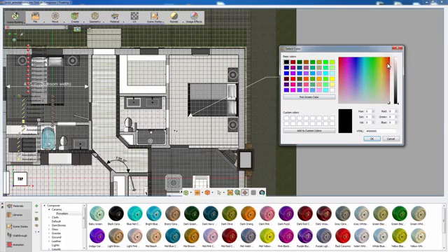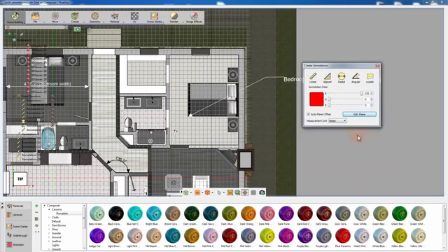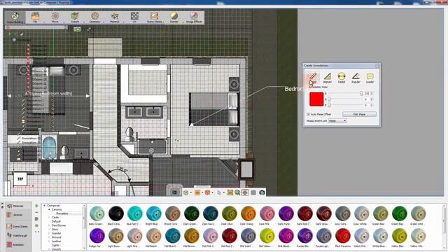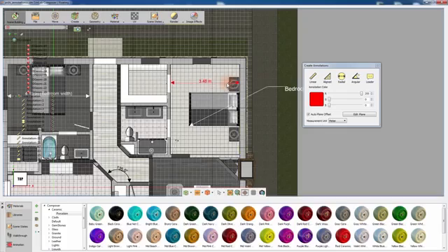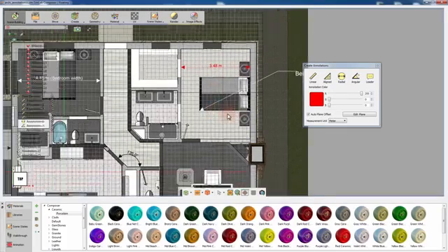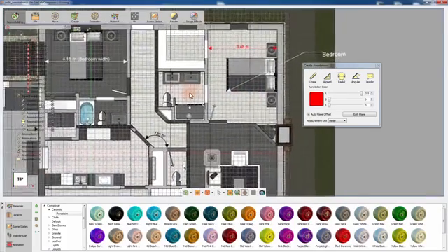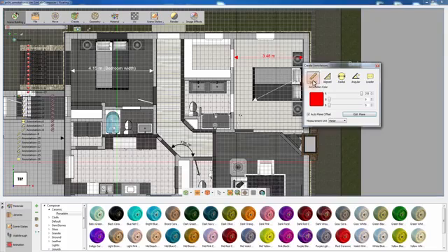Click on the Color thumbnail in the Annotation Creation dialog window and change the color from black to red. Changing the annotation color from the dialog window predefines the color of the annotations that will be created. So instead of changing the color of each annotation one by one after they have been created, you can change the color of those annotations prior to their creation.